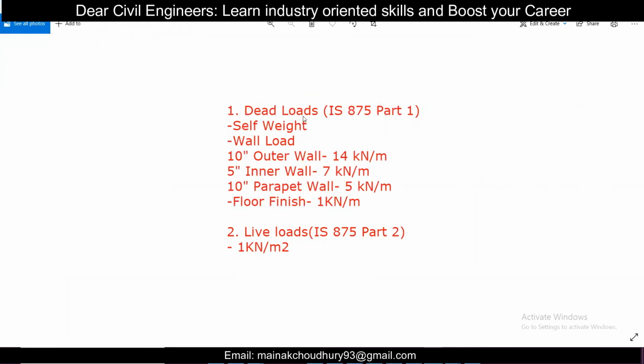For dead loads, the code is IS 875 part 1. We all know that. If you don't know, just remember this, and also watch the video in the ETABS part, so that you can know the basic things you need to remember about this code. Self weight, the software automatically takes. Wall load we're going to put in the software. For a 10-inch wall, we're going to give 14 kilonewton per meter.